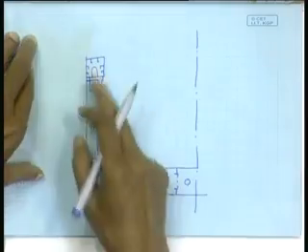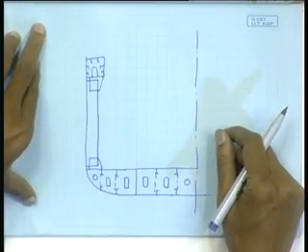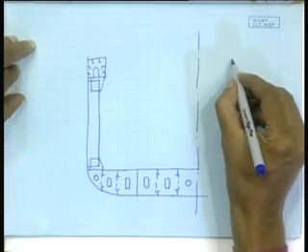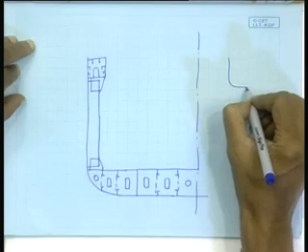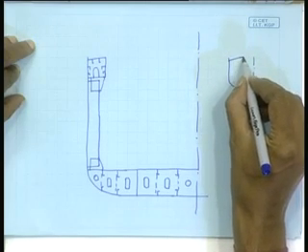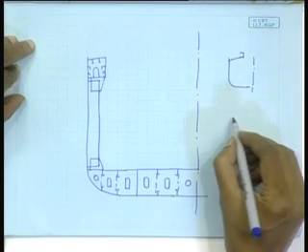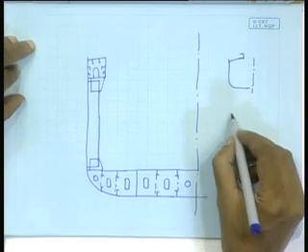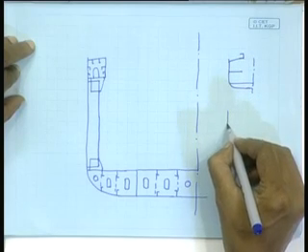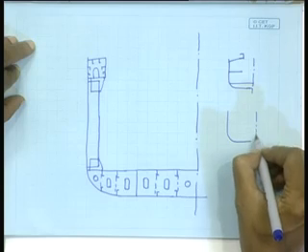We have talked about how we have containerized the cargo because of easy loading and unloading. So, if we have to do that, we will have to have a midship section, something like an open section, means fully open. Till now, all the vessels we have seen, if I make a comparison here, had a hatch opening like this, be it a general cargo carrier or a bulk carrier.